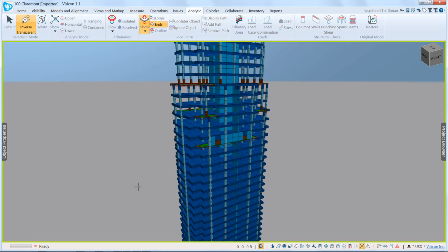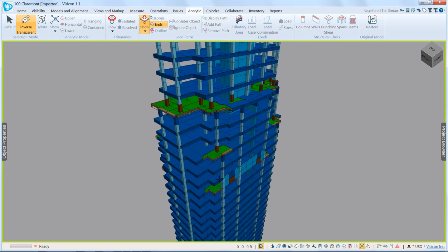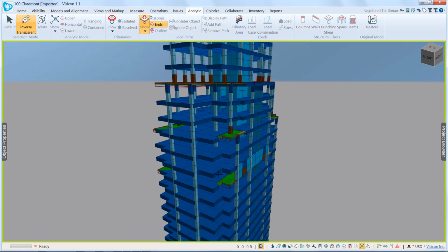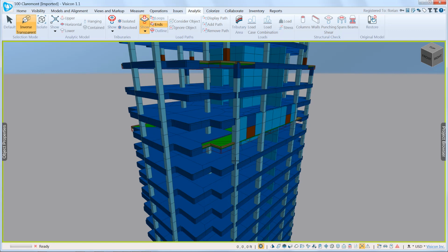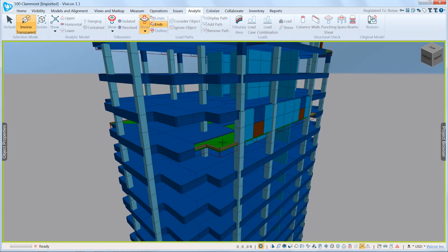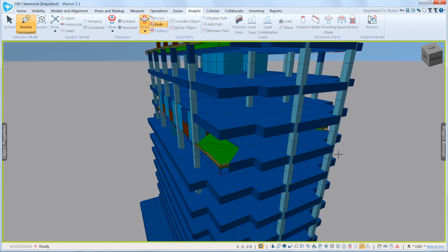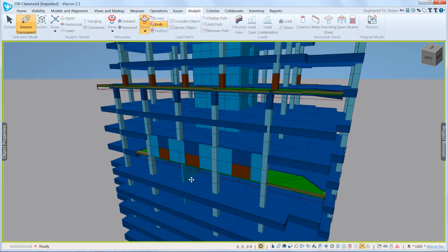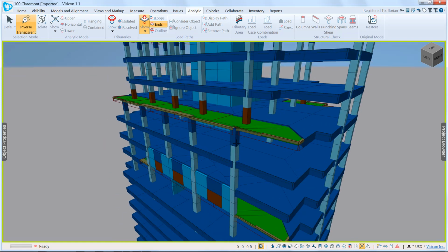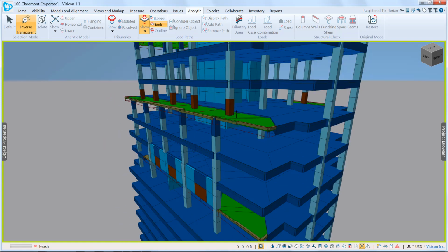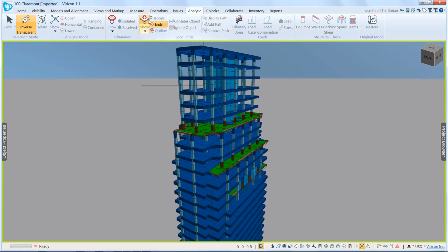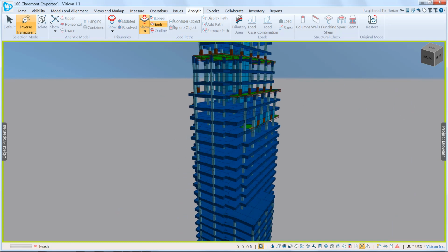So we've now calculated the load path, and the most interesting thing to begin with is here you see the color contrast where the program has identified all discontinuities. So here the reason this particular tributary is tagged as discontinuous is because this wall rests on it. If we look at the other side, again we have the wall component here that's triggering that condition. Here you have a clear transfer of a column that goes from one side to the other, and here we have the same condition.